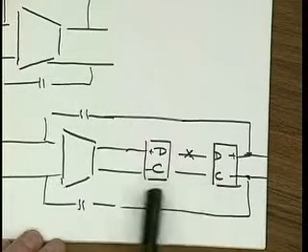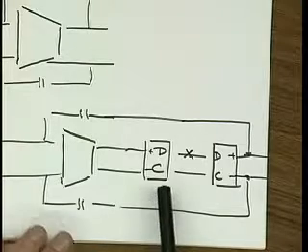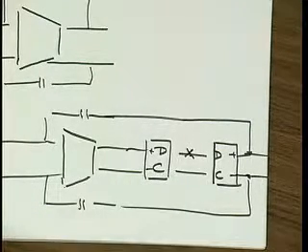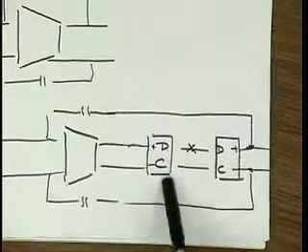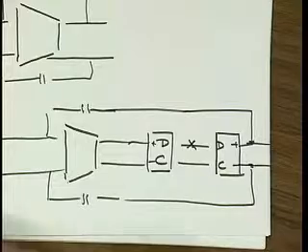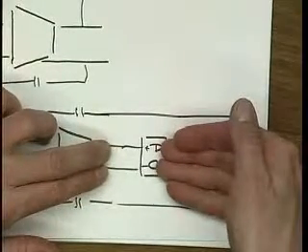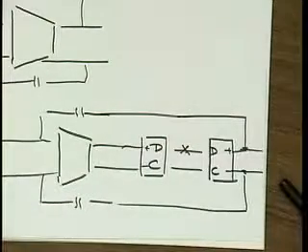Now it also becomes clear why these baluns are so practical. If we had used some kind of a circuit that internally uses controlled sources, ideal sources, to generate the differential mode and common mode signal, that would have been a big disadvantage because the output impedance of that thing would have been 0 and the input impedance probably also, so the loading would not have been preserved.